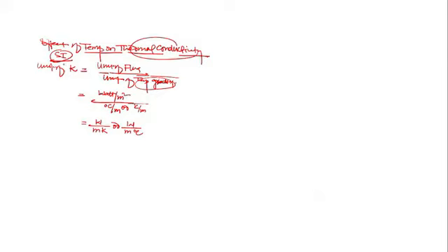As far as the effect of temperature is concerned, first I'm talking about gases. For gases, my dear student, as I told you, the mechanism of conduction in gases is molecular diffusion and collision. Yes or no? And we can increase the diffusion and collision by increasing the kinetic energy, and kinetic energy can be increased by increasing temperature. So as temperature increases, the kinetic energy of the molecules increases, and the molecules will move much faster. So random motion will increase, and due to random motion the energy has been transferred from high energy to low energy and low to high, but the net transfer is from high temperature to low temperature, and that was even in the absence of collision. The energy has been transferred due to random motion of molecules. So if we are able to increase the random motion of the molecules, we can do that by increasing temperature.